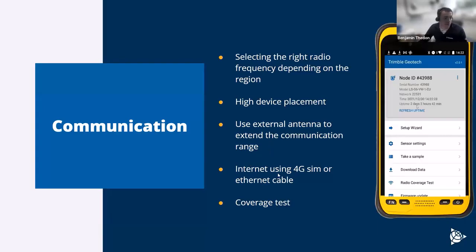It's also very important to check your 4G signal for the gateway to make sure the communication of the sensor with the server is made properly. And also very important when you come on site, check the coverage to make sure you have a proper connection with the gateway.